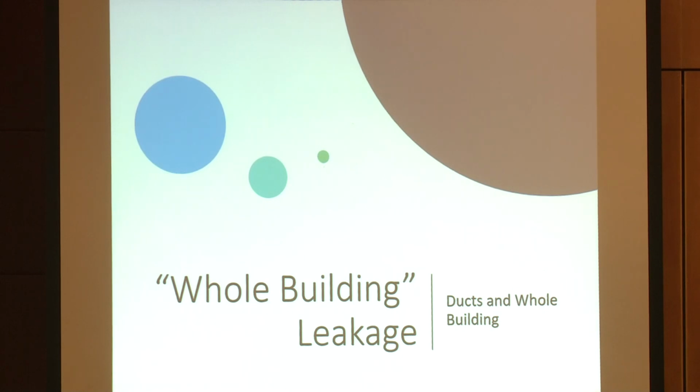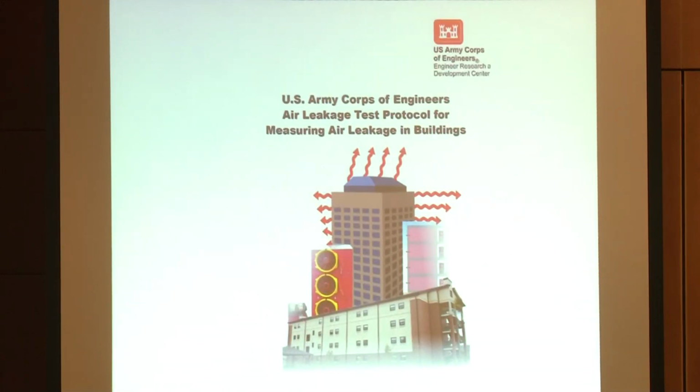The other thing that's becoming incredibly popular is building leakage, right? Testing the building for leakage. Now, I actually had to do this, it's 2006, so I actually had to do this like 15 years ago. It wasn't common back then. It was a government building, and they were the first to specify that buildings could not leak by a certain percentage. And I actually had to pressure test a huge building, and there's no technology available to do it back then, so we had to use the actual air handling systems to actually blow up the building, but we did it.